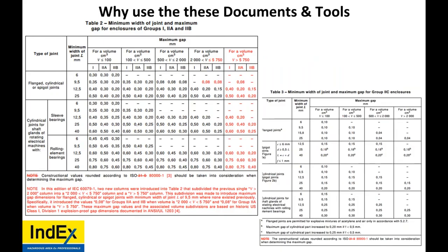Where can we use any electrical parts in an Ex d? In flameproof, you can only use what has been tested and certified. You cannot change anything to anything else. It's only like for like, exact replacement. It's different, Ryan. Only if gas group and T ratings are the same.